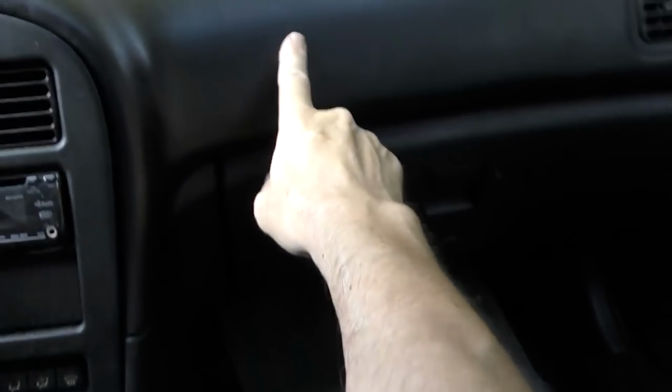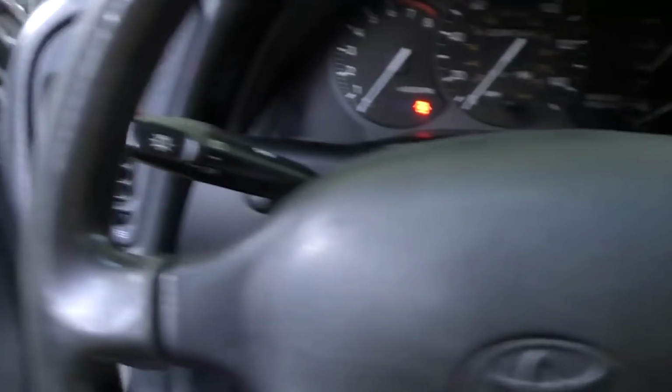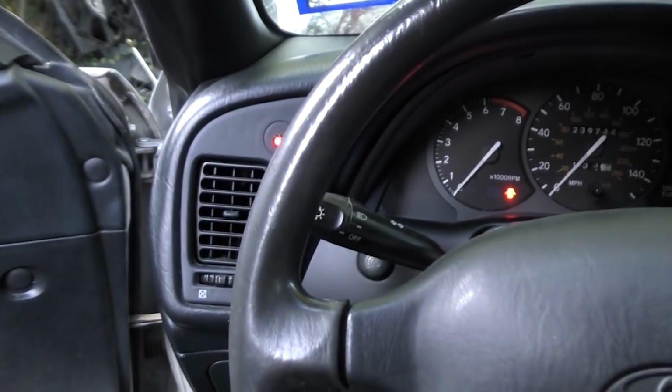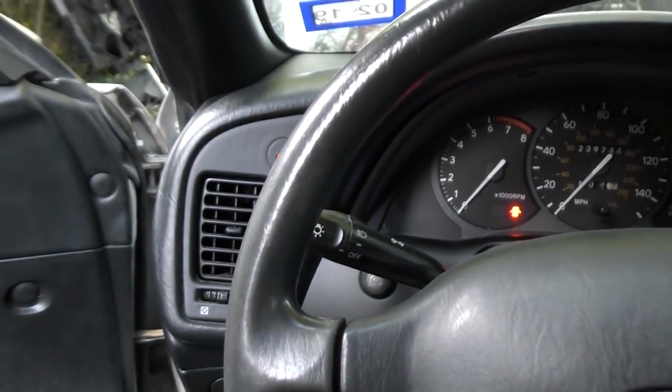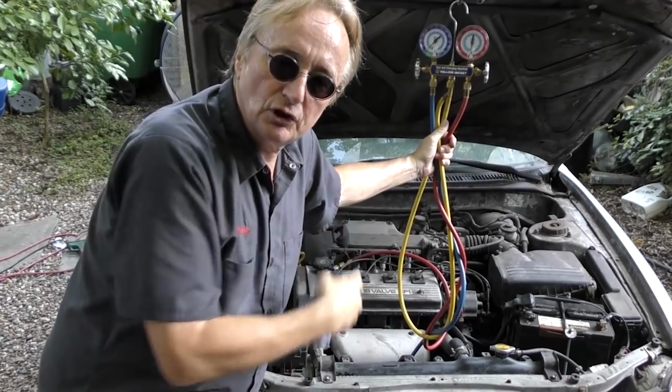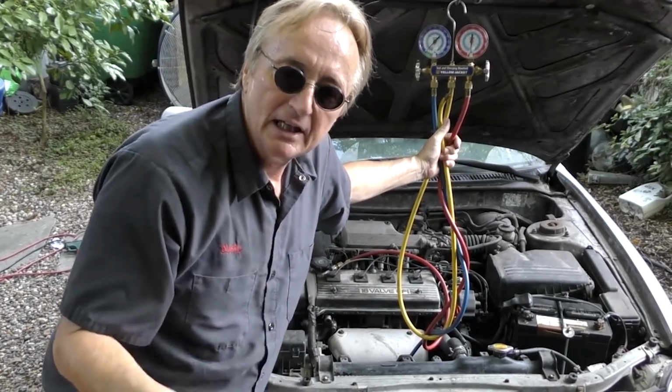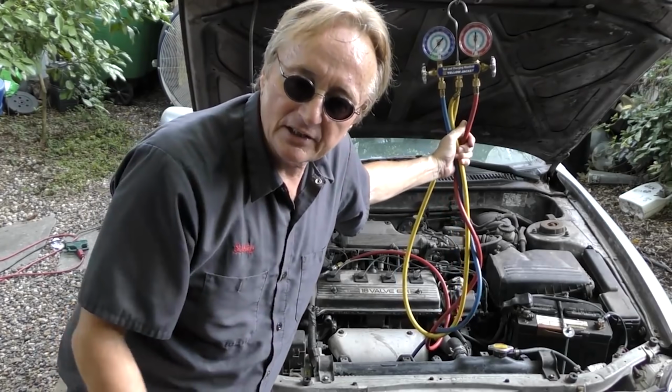And since most cars have the evaporator on the passenger side, if you're running low on refrigerant, the passenger side can still blow somewhat cool, but by the time it makes it over to the driver's side, it's not cool anymore. So just being low on refrigerant can make it do that. So if you know how to use AC gauges, you can hook them up to see if you're low on refrigerant, and if you are, you can add some. And if you don't, you can just pay a mechanic to check it.